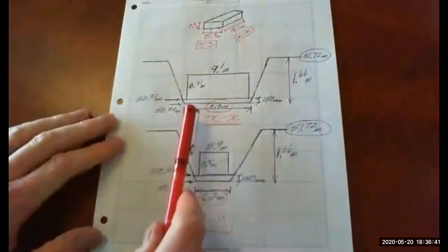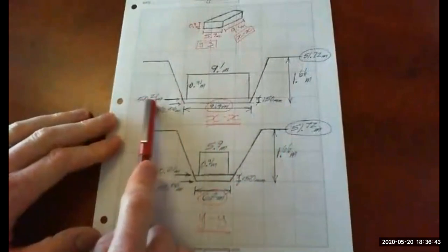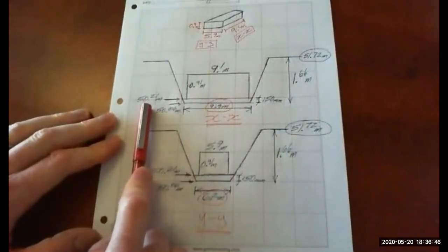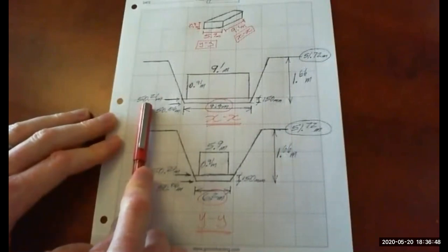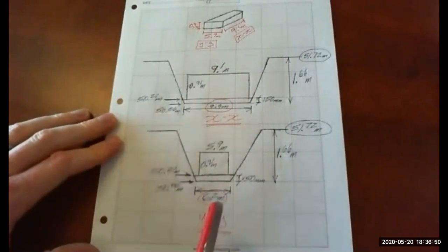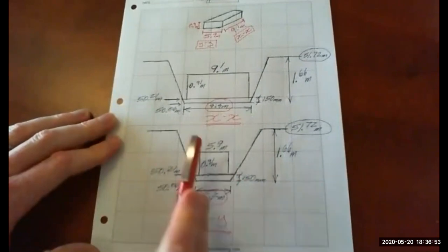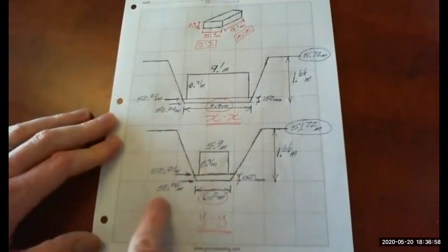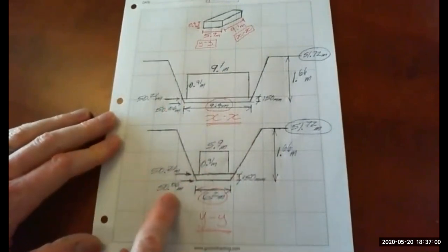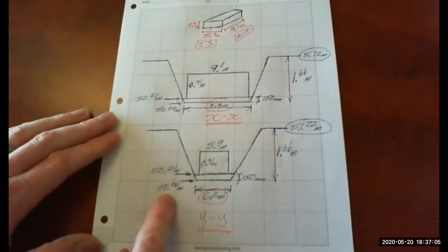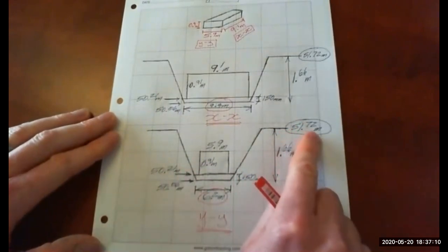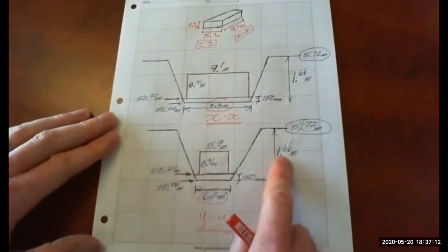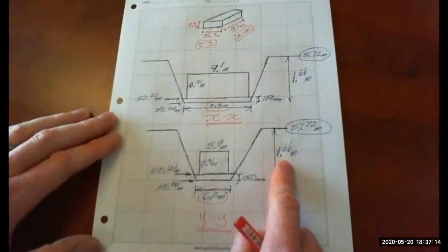So what else have I written here? We're told what the invert of the tank is. So this 50.21 meters. You needed to deduct your 150 millimeters of gravel. So you needed to be lower by 150 millimeters. So that means your bottom of excavation was at elevation 50.06. The difference between that bottom excavation and your finished grade up here is your excavation depth, which is 1.66.